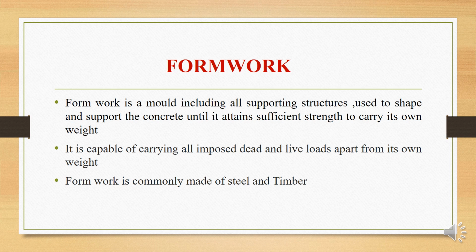What is meant by formwork? Formwork is a temporary structure which has to be built for any concrete member. Basically, formwork is a mold including all supporting structures used to shape and support the concrete until it attains sufficient strength to carry its own weight. It is capable of carrying all imposed dead and live loads apart from its own weight. Formwork is generally made of steel and timber.